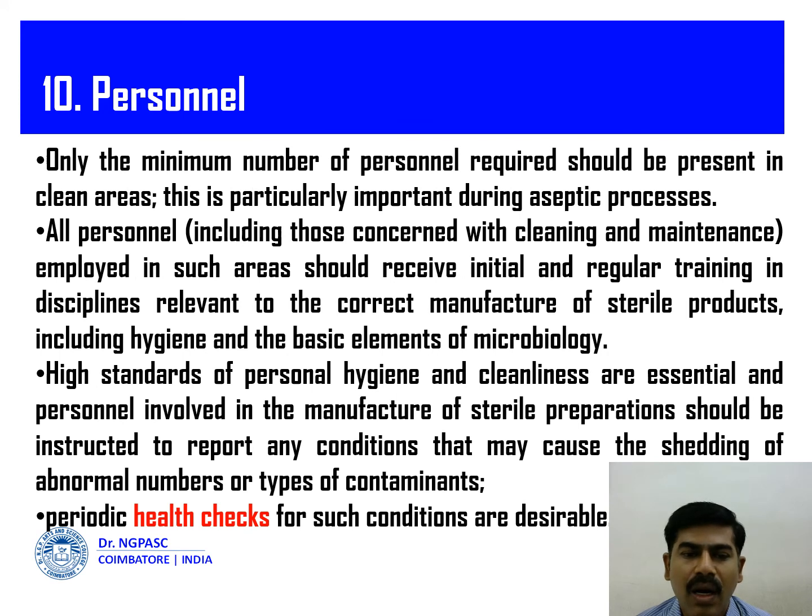In the personnel, only the minimum number of personnel required should be present in clean areas. This is particularly important during aseptic processes. All personnel employed in such areas should receive initial and regular training in disciplines relevant to the correct manufacture of sterile products, including hygiene and the basic elements of microbiology. High standards of personal hygiene and cleanliness are essential, and personnel involved in the manufacture of sterile preparations should be instructed to report any conditions that may cause the shedding of abnormal numbers or types of contaminants. Periodic health checks are required to maintain the health of the process.